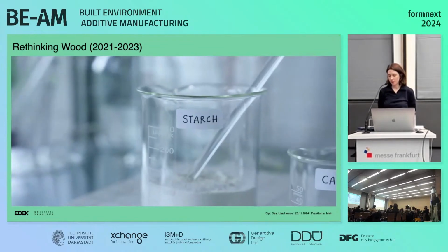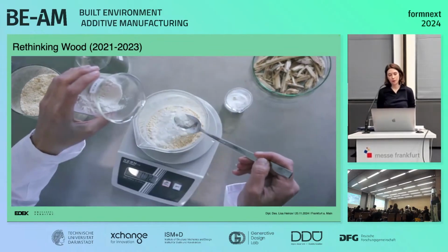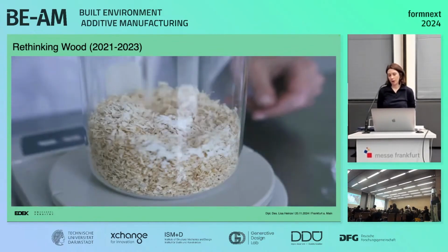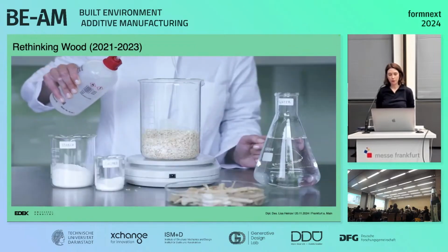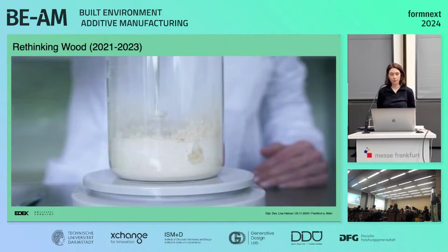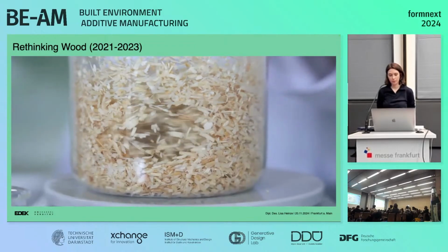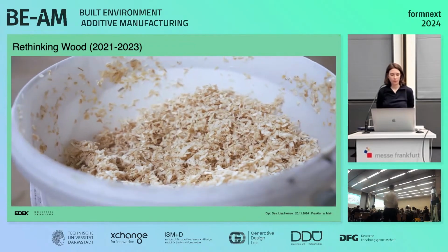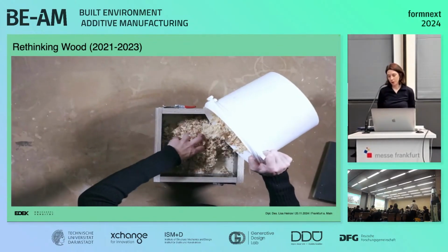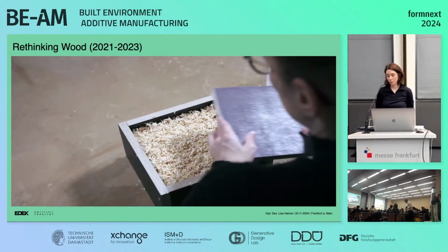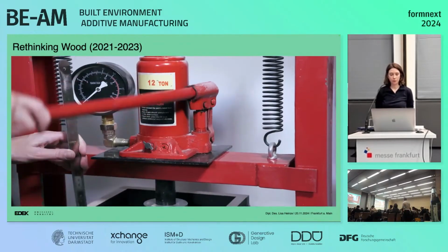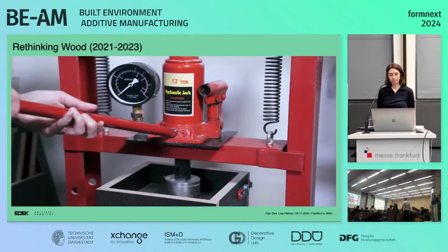And the fibers are mixed with water and the additives just to activate the binder, so the amount of water used is quite small. And finally, the mixture is put into a mold, any kind of mold basically, and pressed into form.